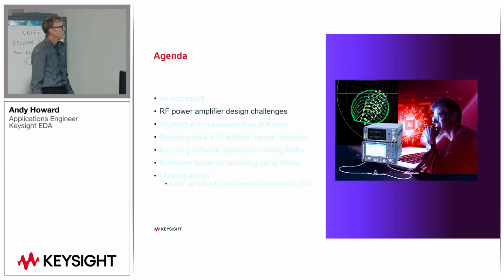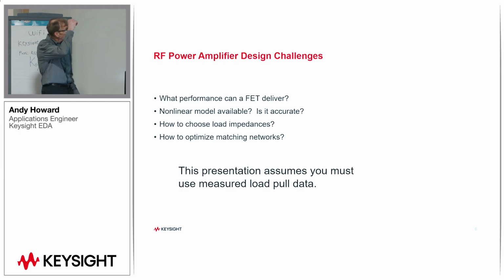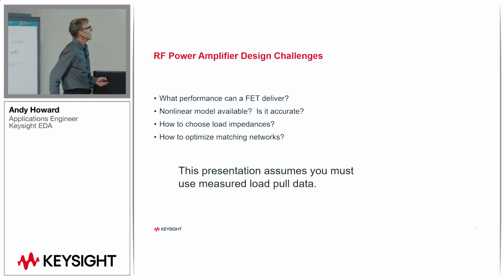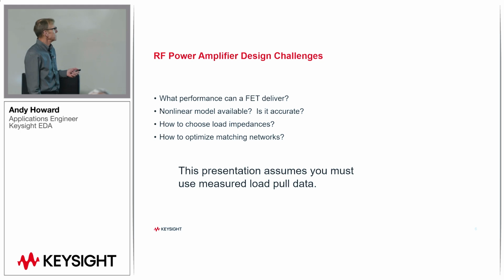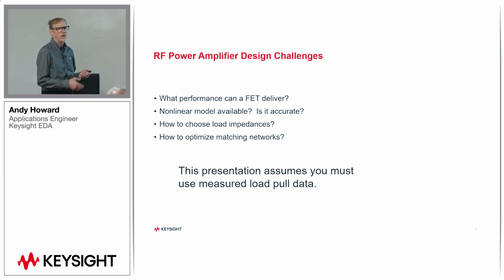I'm going to talk about some of the design challenges that RF power amplifiers face. As a designer, you have to choose a transistor to use, and you need to know what sort of performance could be achieved from a particular device. You can get that from a data sheet or from reading in measured load pull data and examining it within ADS.